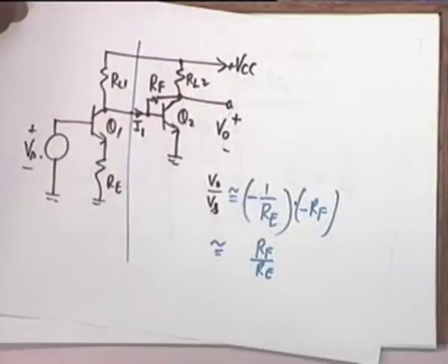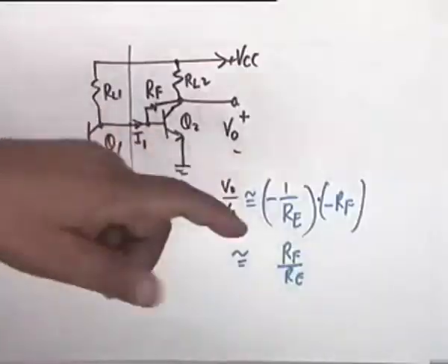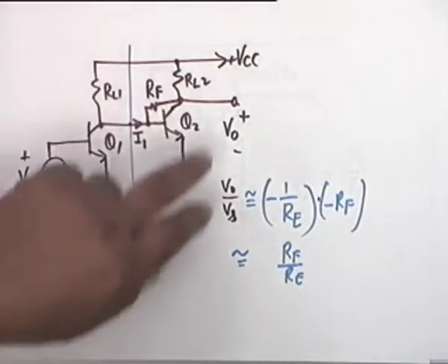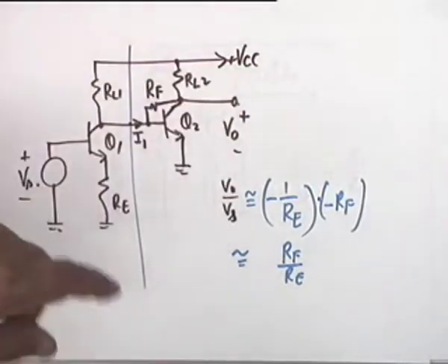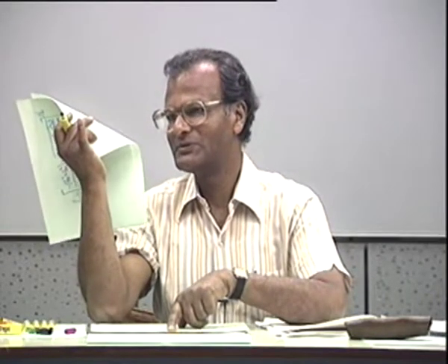This is a voltage amplifier. Why should I increase the current output? Fan out criteria. No, that's not it. It's simply another buffer, another common emitter stage, so that if you connect a source here, you see, even with this, the output impedance is not zero. Isn't that right? We calculated the typical value was 234 ohms or so.